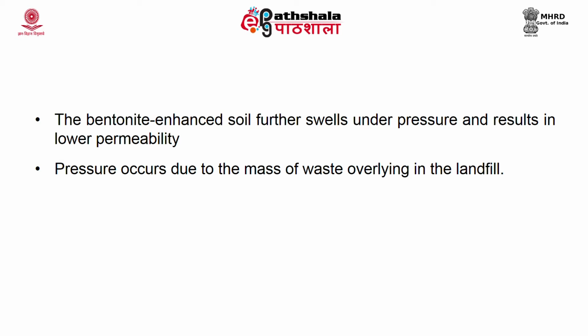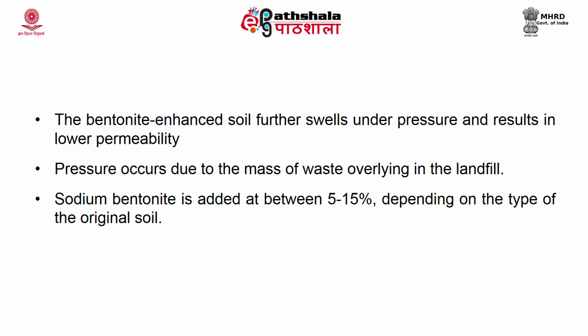the weight or the mass of the overlaying waste will also create a pressure. It will put a pressure on this bentonite clay. When it puts a pressure, obviously again it will start swelling. This is the beauty of a bentonite clay material. So, again it will lead to lower permeability. Sodium bentonite, as I told you earlier, has lower permeability. It is added in the range of 5 to 15% and is blended with the soil. This 5 to 15% will again depend upon the type of original soil which is to be used.